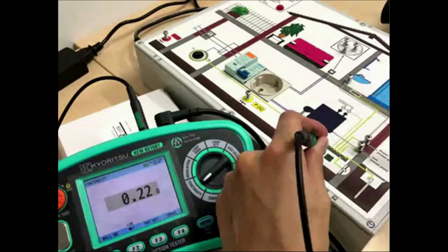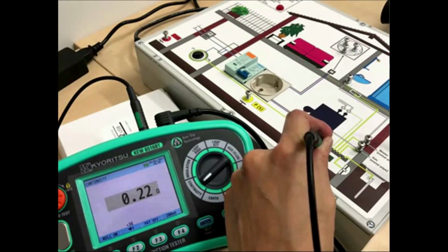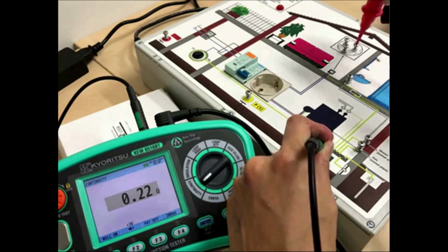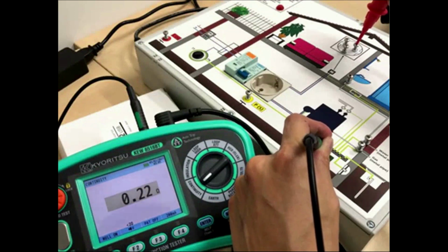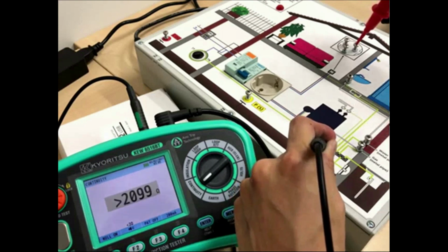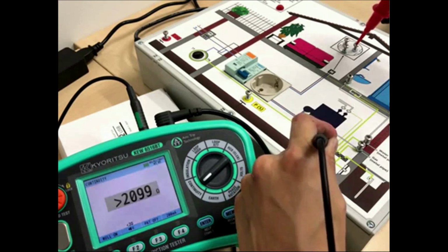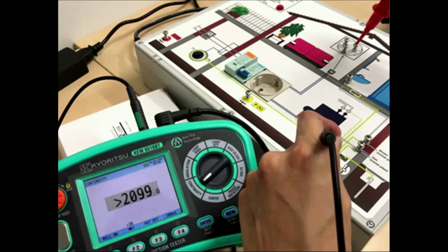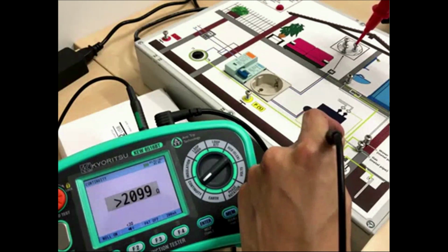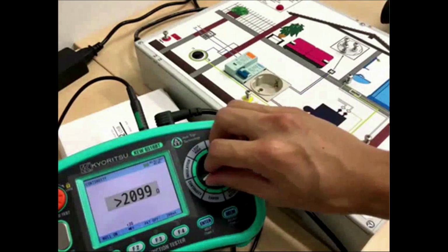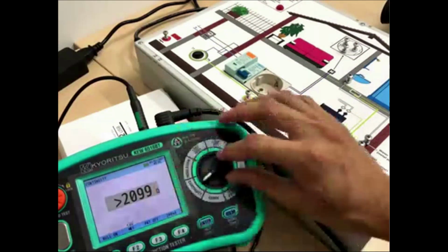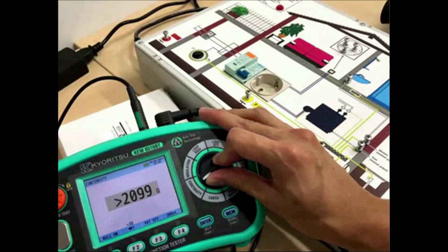Okay, for example, your wire breaks. You go and test the neutral. Neutral and the earth do not connect to each other, so it means it's an open circuit. To test, see what's the result? 2000 ohm, over 2000 ohm. So mean to say, if you see this condition, your wire is no longer continuous. You understand? Now we go to another function. Continuity, I think you all know already.